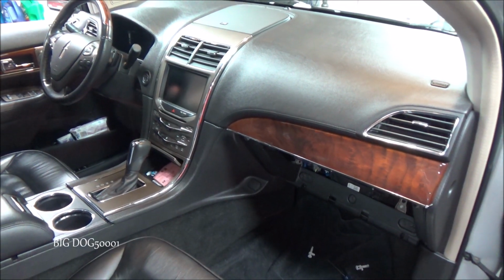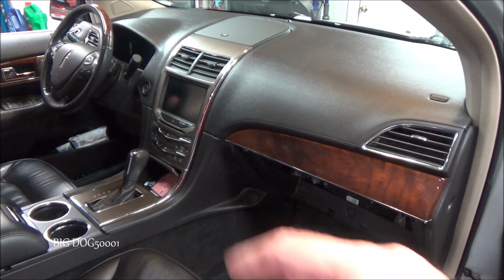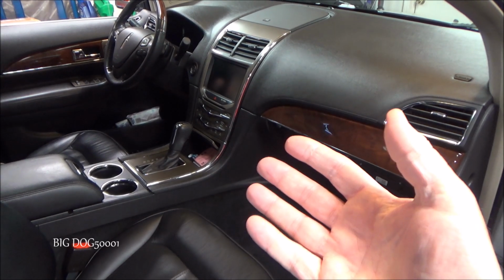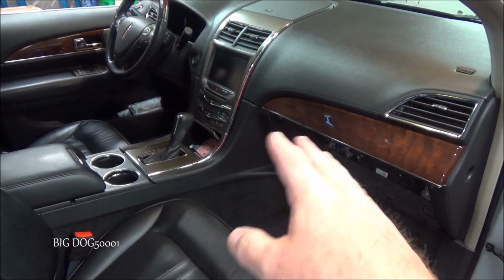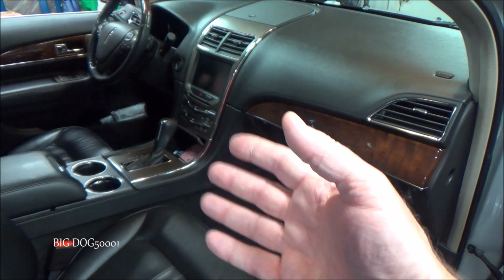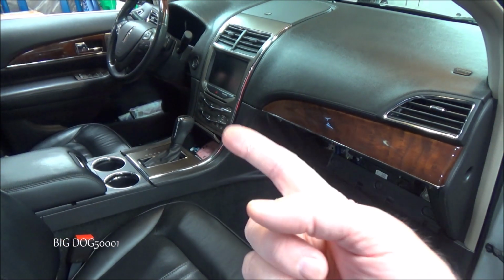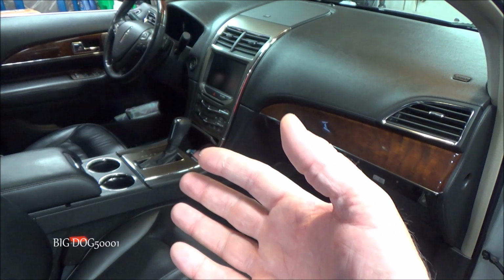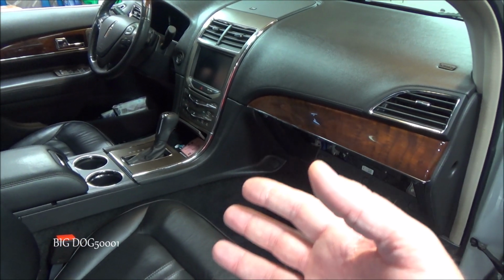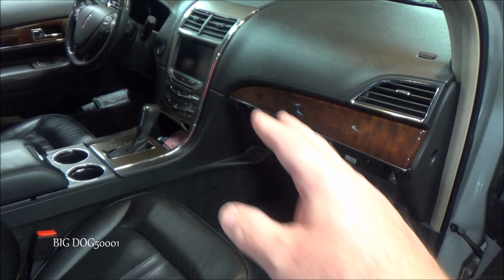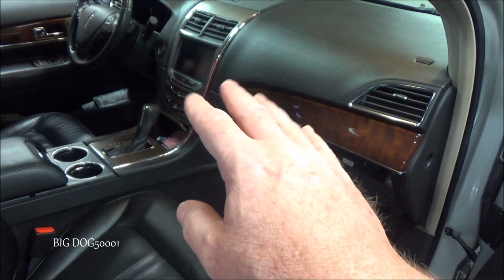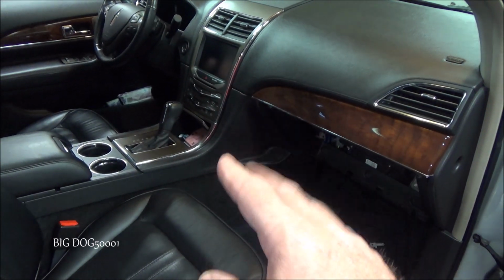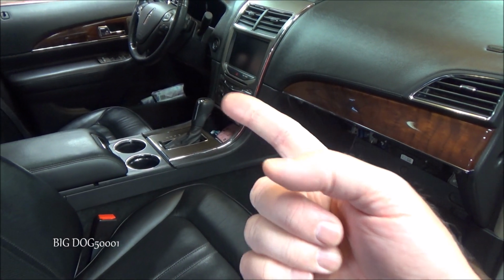I'm trying to give you some tips or things that I think about when I'm dealing with this. There are three things I try to keep in the back of my head when it comes to dealing with uneven hot and cold situations. The first thing is, is it an AC refrigerant issue? Basically low refrigerant, moisture or air in the lines, or a restriction. Any of those things could cause an uneven heating and cooling situation, at least as you would perceive it. That's the first thing I keep in my head.